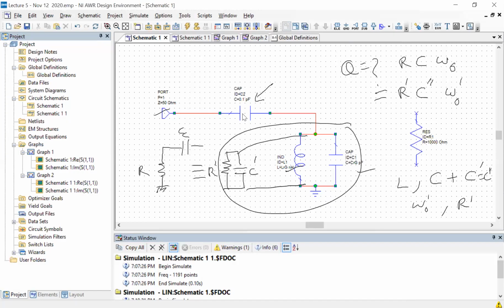There could be some million other ways I could have written this equivalent circuit. Why did I choose to write it like this? Initially we chose it because we wanted a similar expression for the quality factor. That is the justification, but you can also think about it differently. We know, at least from observation, that the resonance looks more or less the same, except for these phase shifts. So if everything is the same, there should just be a new effective R here. That is the thing we were trying to target.